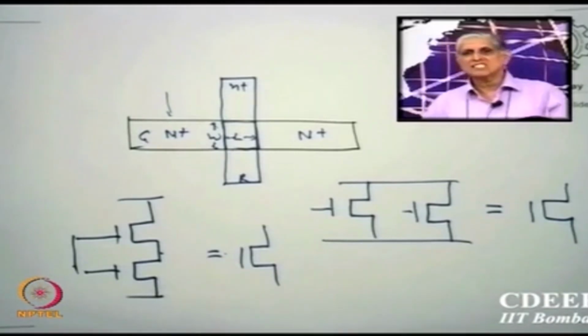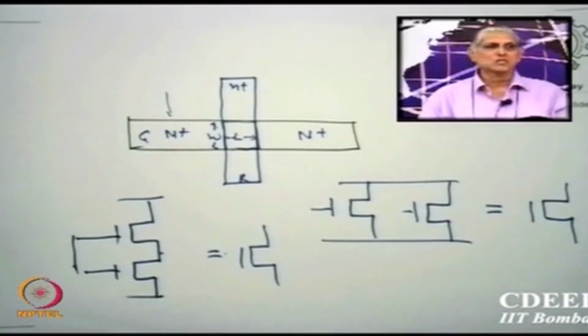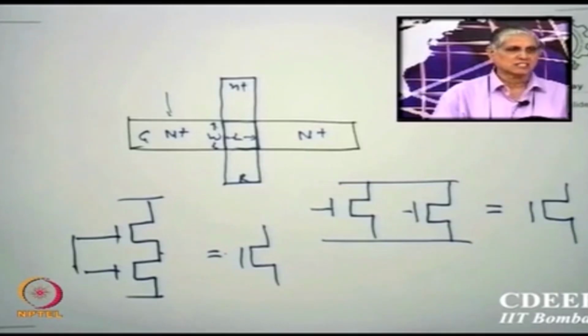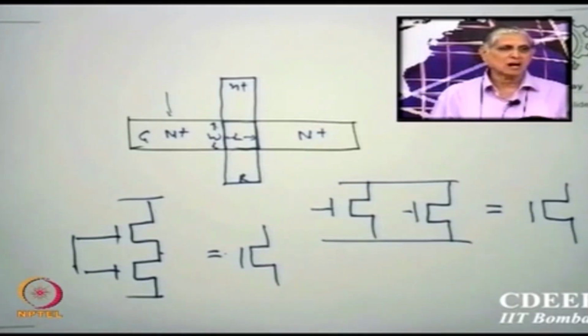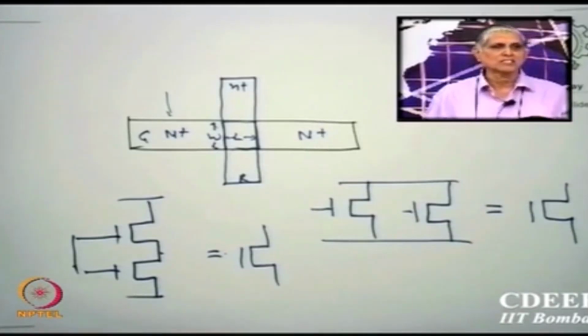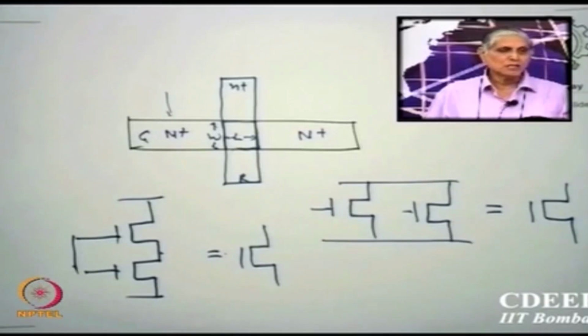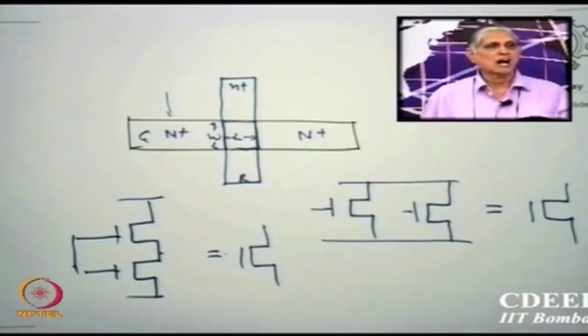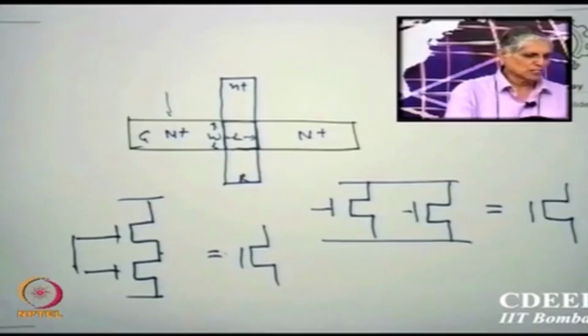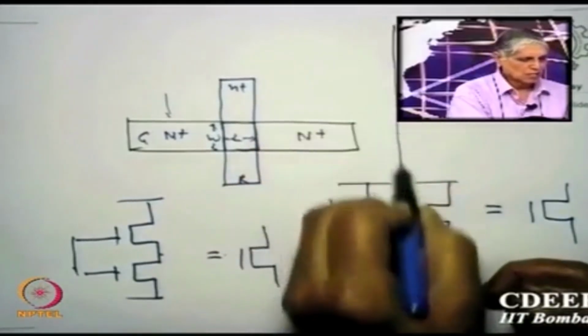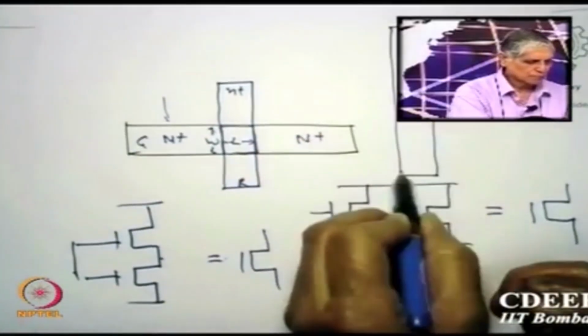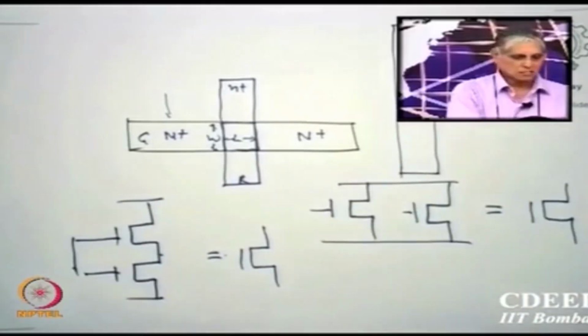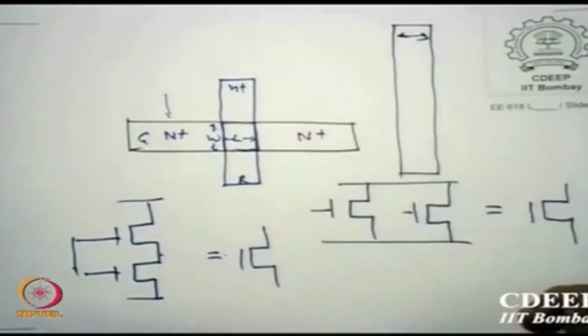So for transistor sizing, normally do not put huge size transistors. Break them into either series or parallel combinations, so that the uniformity of each is much more maintainable. There is a word we use in layout called aspect ratio. Let us say this is the line, the length. This is small, much smaller compared to this.